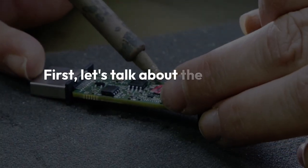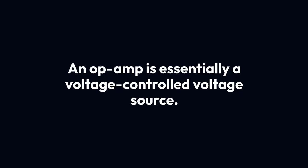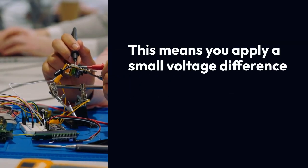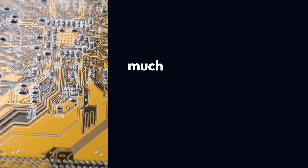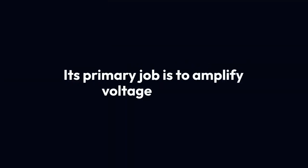First, let's talk about the op-amp, or operational amplifier. An op-amp is essentially a voltage-controlled voltage source. This means you apply a small voltage difference to its inputs, and it produces a much larger voltage at its output. Its primary job is to amplify voltage signals.